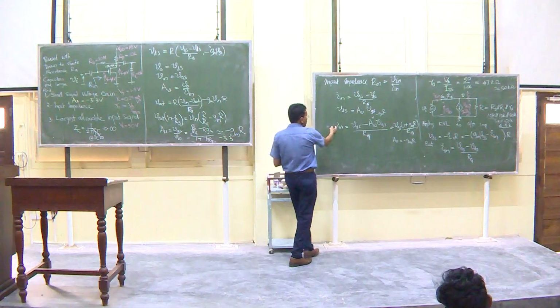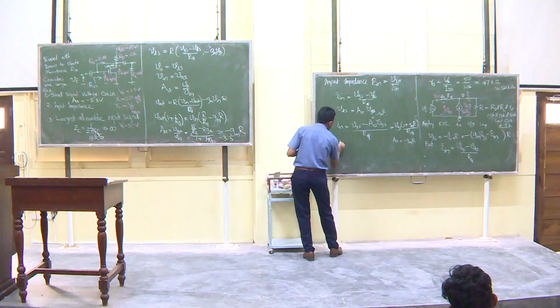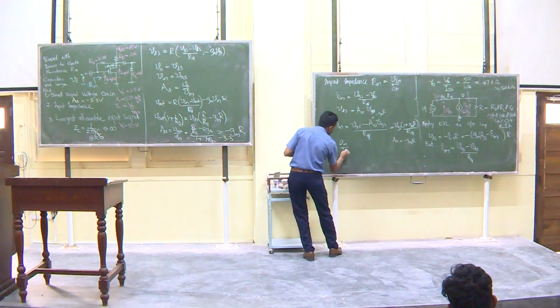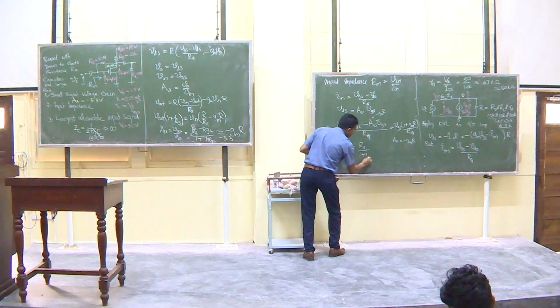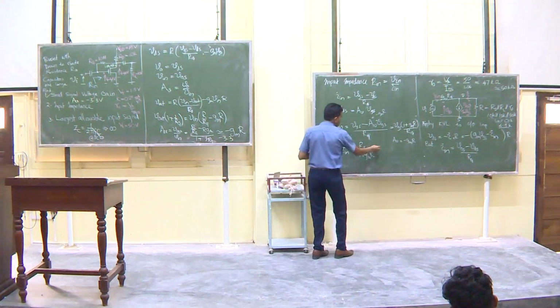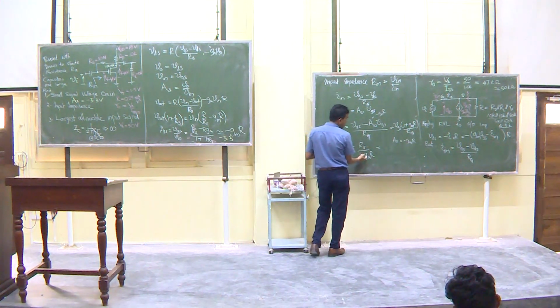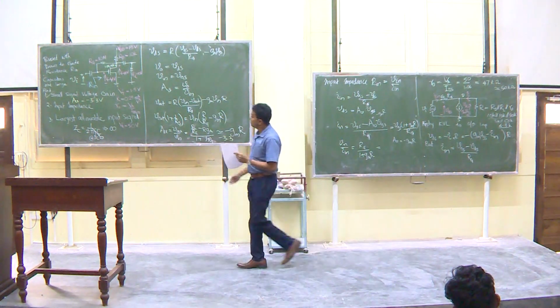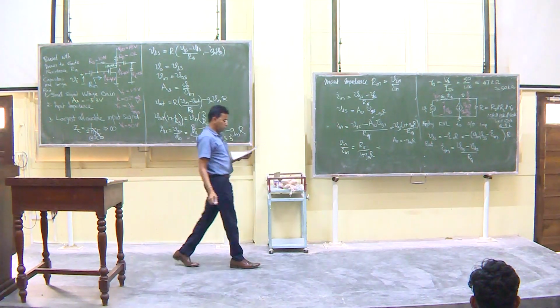So therefore, the V in divided by I in ratio is equal to RG divided by 1 plus GM R. If you apply the values, R is 4.5K, and GM we calculated earlier, 0.725.